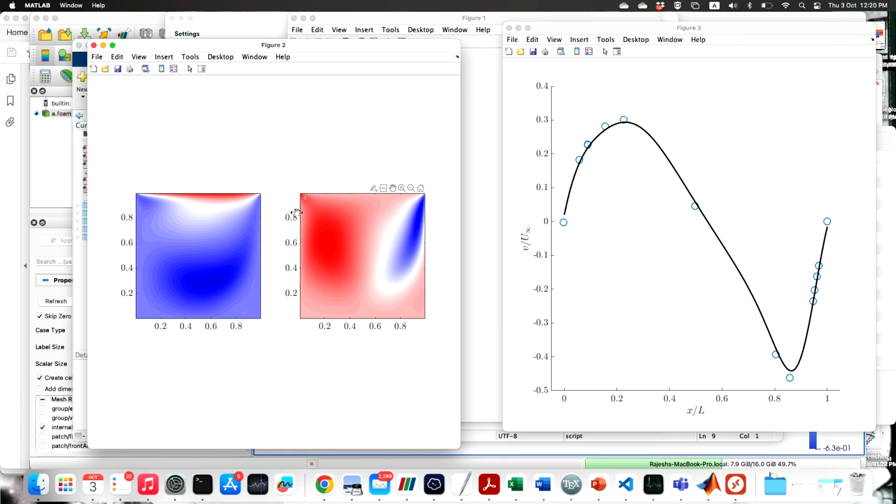So at the midpoint of y here, from here to here I am plotting, and you can see that it goes high and then comes down, that is the red region when it goes high and the blue region when it goes low, right. The left one that you see is a qualitative plot, which makes sense. First thing whenever you do a simulation, you have to qualitatively see whether things are making sense: when my top lid is moving, whether the flow that I am expecting because of the movement is coming or not.